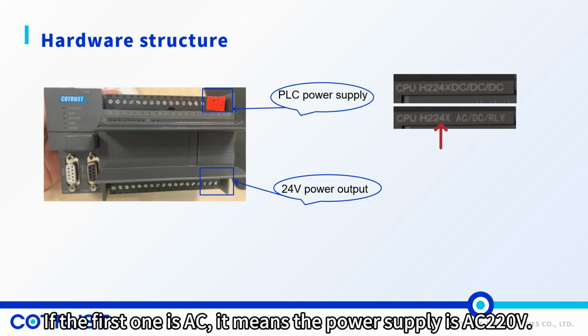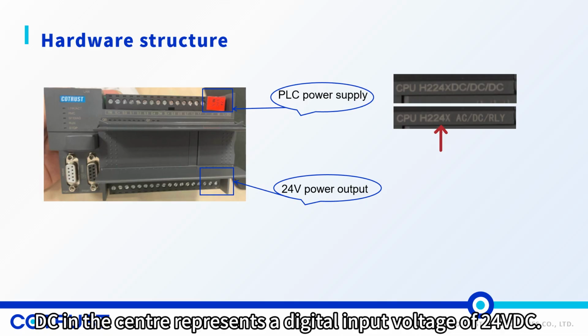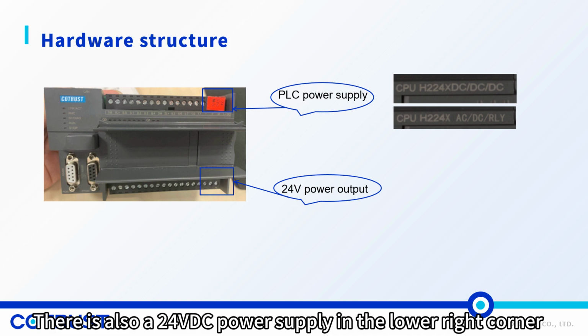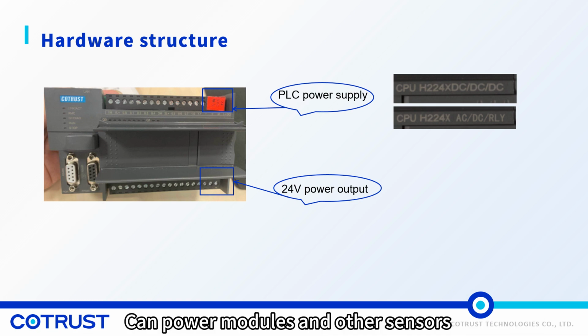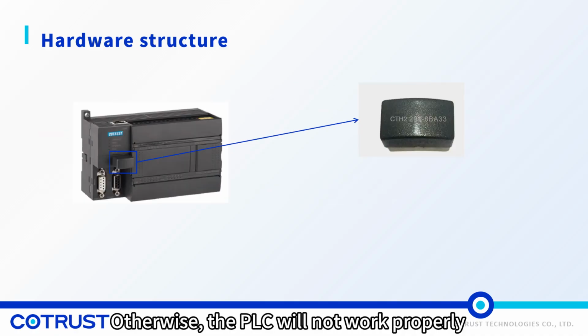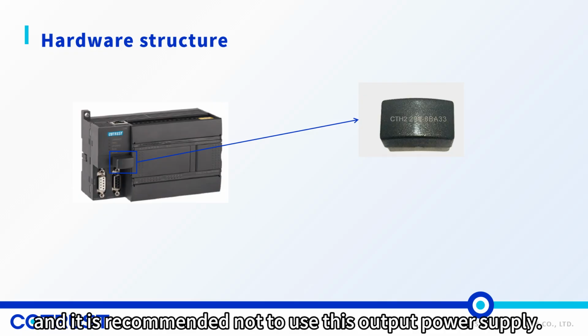If the first one is AC, it means the power supply is AC 220V. DC in the center represents a digital input voltage of 24 VDC. RLY means the output is a relay output. There is also a 24 VDC power supply in the lower right corner. It can power modules and other sensors. Be careful not to exceed the maximum output current it allows. Otherwise, the PLC will not work properly, and it is recommended not to use this output power supply.